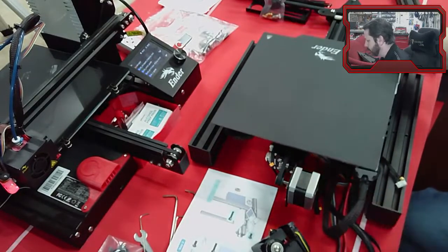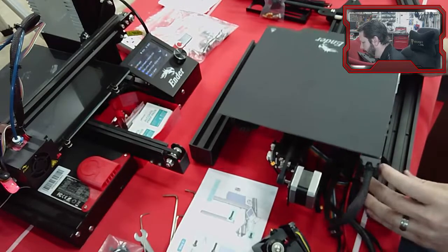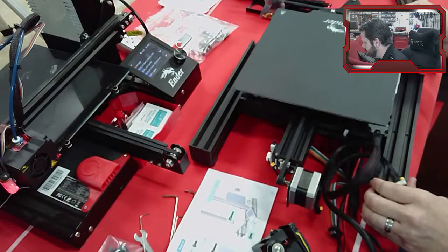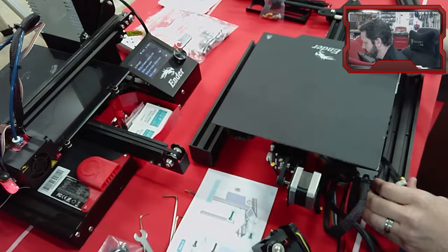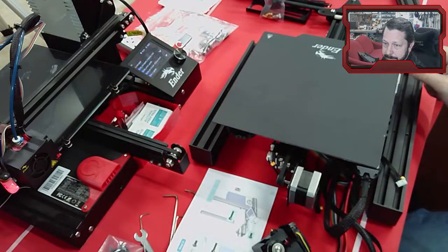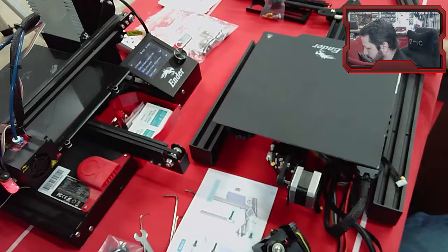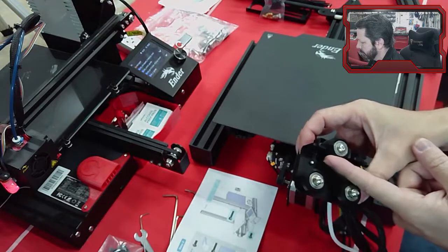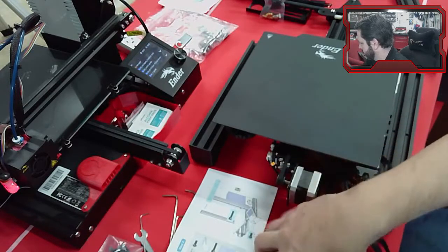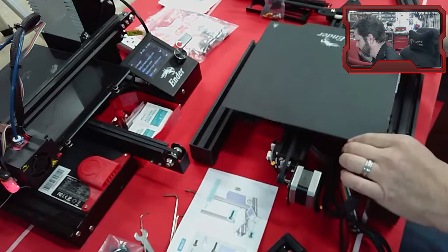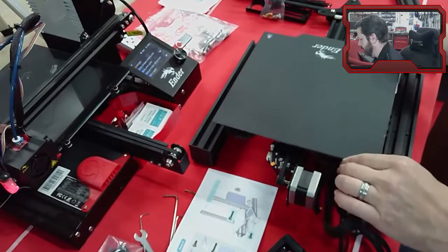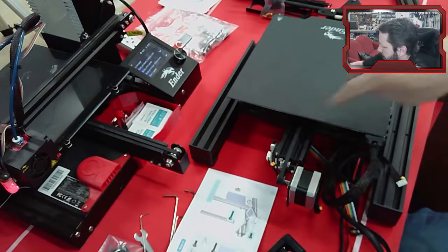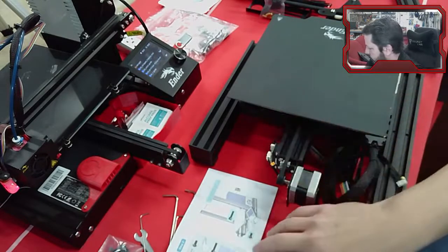Now, as I'm moving this, I can already feel it, maybe you can see how it jerks? Like there, it just stops. What they've done here is they put one of these eccentric nuts on so tight that one of these wheels has a flattened spot on it. So I'm going to have to work on that because it's kind of clunky. I'll go in later and loosen up one of the eccentric wheels underneath here.